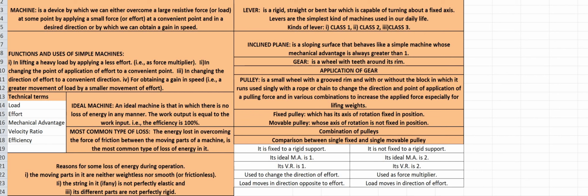Now the wheel B of the minute arm is connected to another wheel C with the gear ratio NB is to NC, which is equal to 1 is to 12, and the hour arm is attached to the shaft of the wheel C so that for one complete rotation of the wheel of the minute arm, the wheel C of the hour arm moves by one tooth.